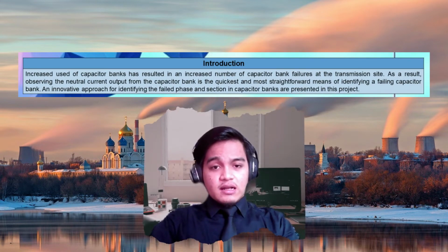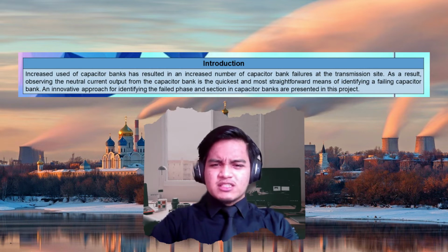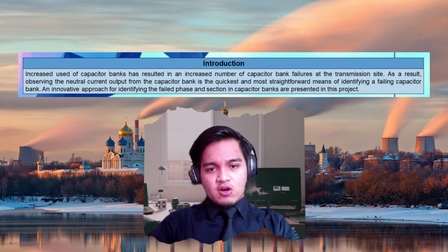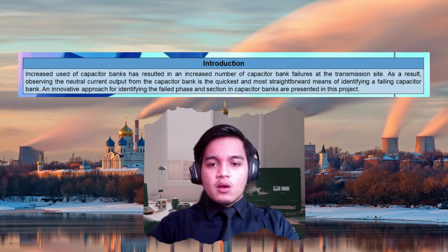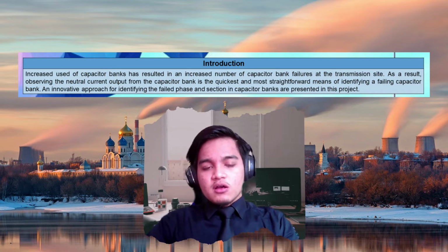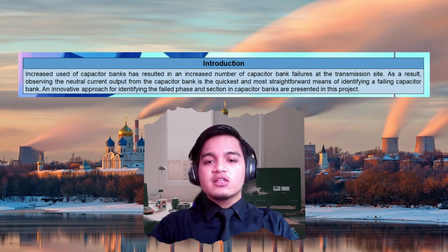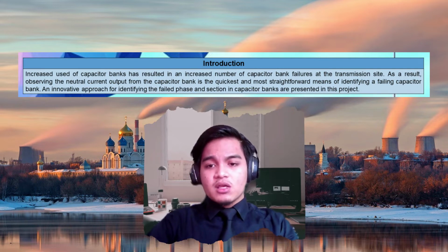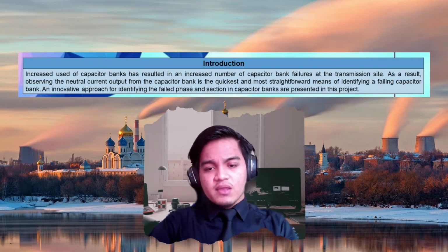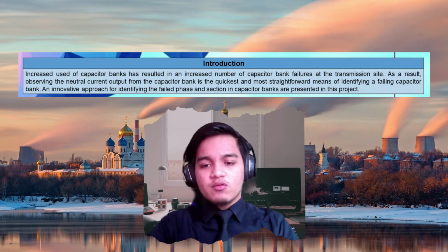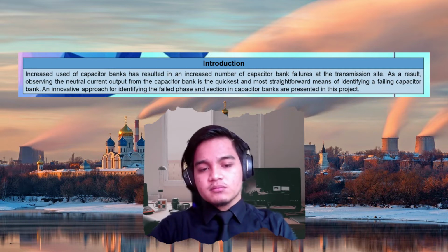For the introduction, the Shunt Capacitor Bank (SCB) is always situated close to the main substation to compensate for capacitive reactive power of electricity. When a higher power factor is achieved, the power loss will be minimized. In this modern era, with contemporary technology and the rising use of electrical equipment with motors, the power factor at the transmission side will constantly be in a lagging condition, and this must be corrected to ensure that the electricity utilization efficiency is always close to the ideal power factor.